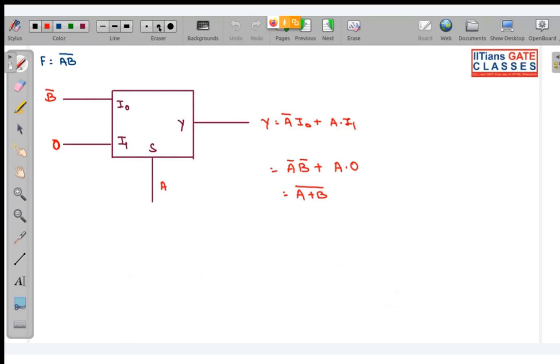So look very carefully at what I take. Let us take 1 over here. If you take 1, what will happen? This will be A complement dot B complement plus A. Again use the distributive property. One B complement. Now if you solve this, this will be A complement dot 1 plus A dot B complement. Now solve this using the distributive property. So A complement plus A